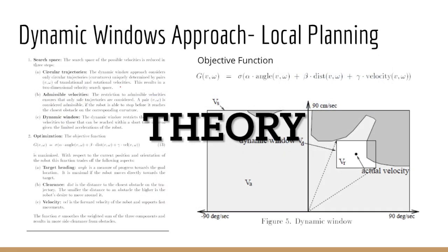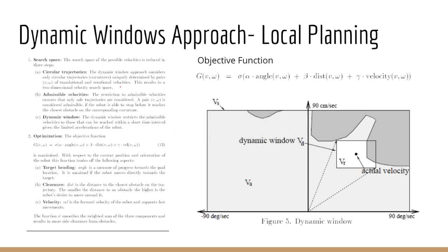I'll be referring to the dynamic window approach by the acronym DWA. The DWA is derived from the motion dynamics, so it's good for robots operating at high speeds, like a car, in this case, and the Roar project. It only searches for velocities in the dynamic window, which consists of velocities reachable within a short time period, and in this case, it's 0.25 seconds.